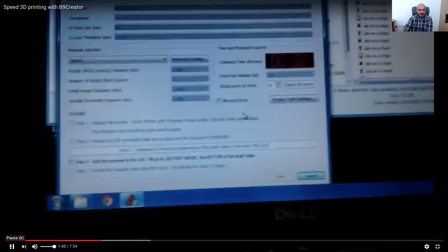Doing some operations for the next layer. Yes, this is underneath the printing system. This projector is projecting some white and black regions. White regions will be cured with the help of the light, but the black regions will not be cured. Now they are playing with the focus of the projector, and this is the top side. This is the tray. The part is actually built here. After each layer, it performs such motions to do some cleaning. Not a complicated operation, and here you see the liquid polymers.